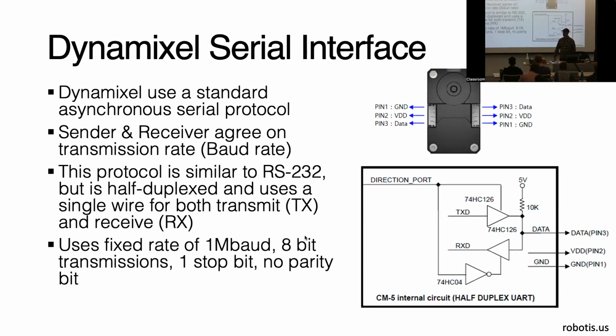All right, so inside these motors, we communicate to them with a serial interface. So you'll notice a little box at the back of the motor that we plug in with USB. That's doing the serial conversion to the Dynamixel serial bus, all right? So each motor has 2 ports, and then there's 3 pins on each side. They're basically in parallel.